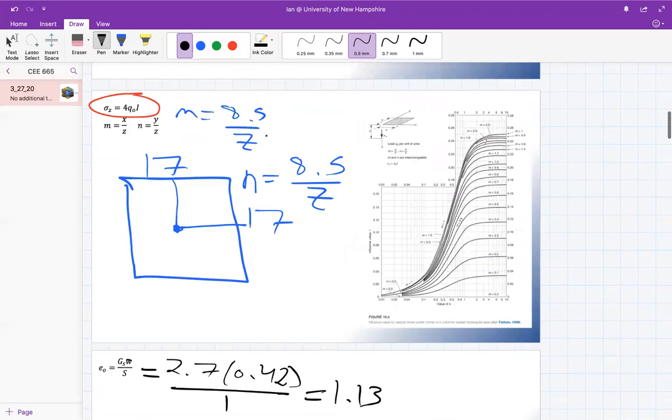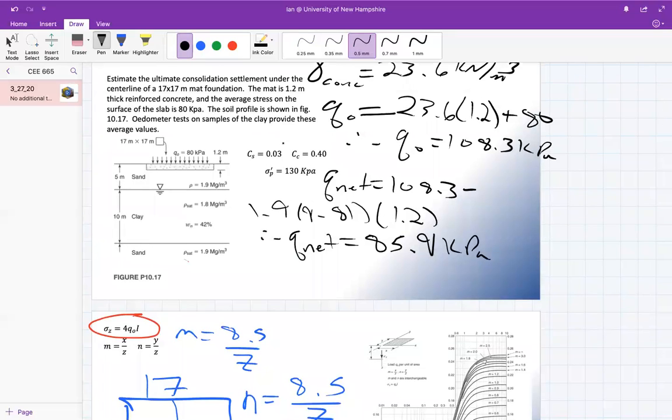Now, these parameters are gathered from your consolidation test. And we're going to adjust them a little bit using the void ratio so that they're in relation to strain. And this is your compression curve index, and this is your swell or recompression index value.